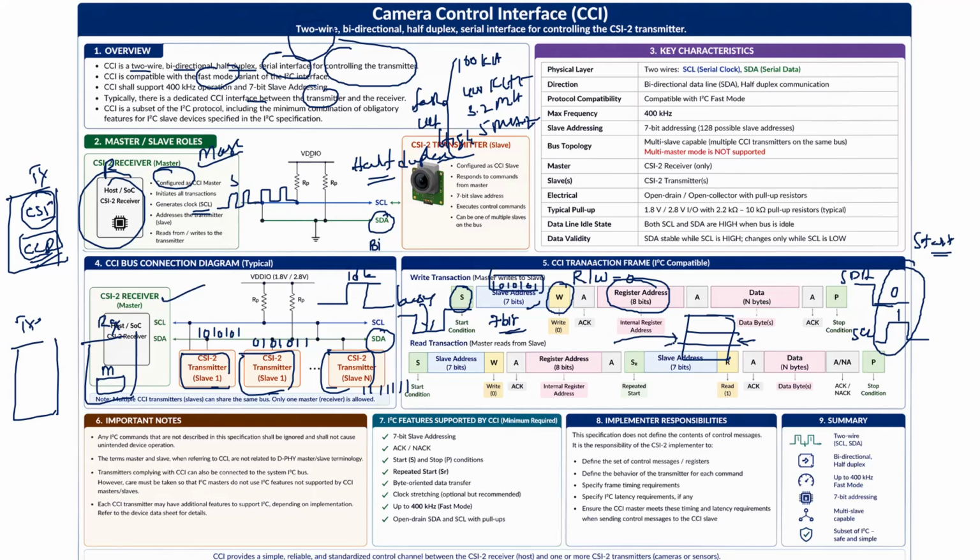That means wherever you are storing the data, there is an internal register, and then we will receive the acknowledgement bit. If you are receiving the acknowledgement bit, it means the address was successfully placed, and then I am placing the data. So n data bytes we are transferring. 8-bit data is 1 byte. After every transfer of a data byte, we need to send the acknowledgement bit. That means whether your data is transmitted successfully or not, based on the acknowledgement bit only we will know.